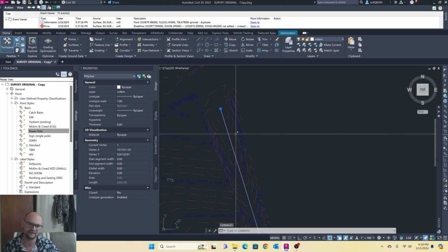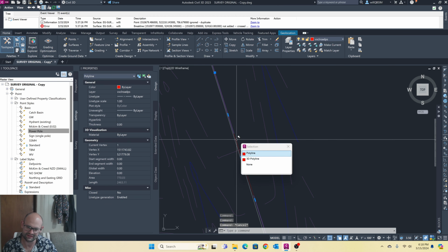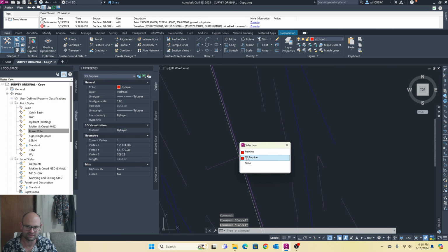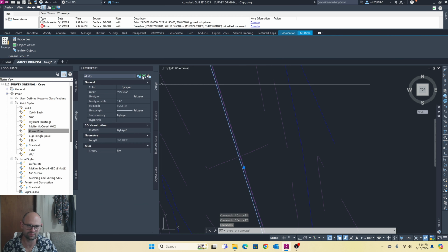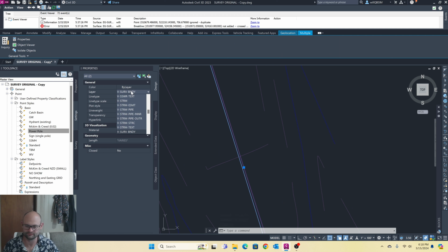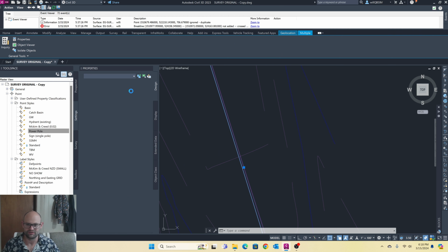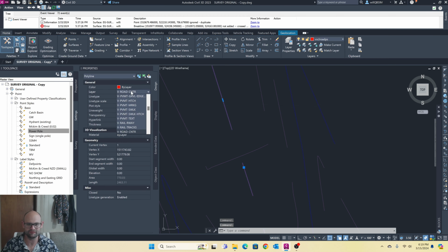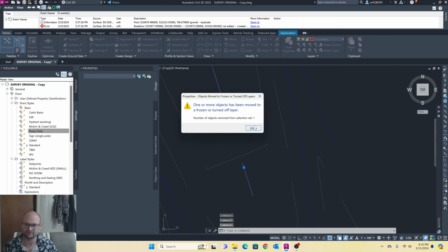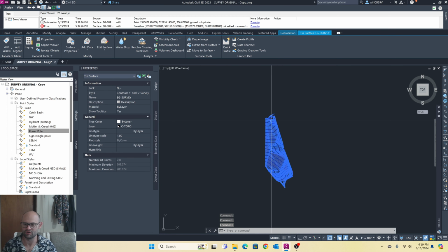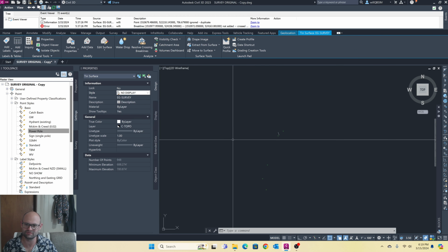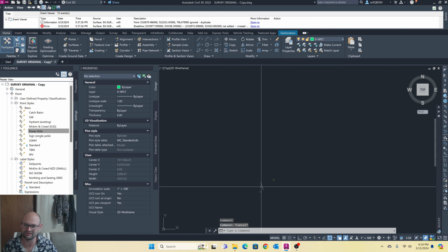That's a polyline. It looks like it could be the center line, but this does too. So road, those are both break lines. I'm gonna do survey mesh for those. And then I'm gonna take this center line and put it on V road center for topo here. Just gonna move that to no display. See what we have left here.